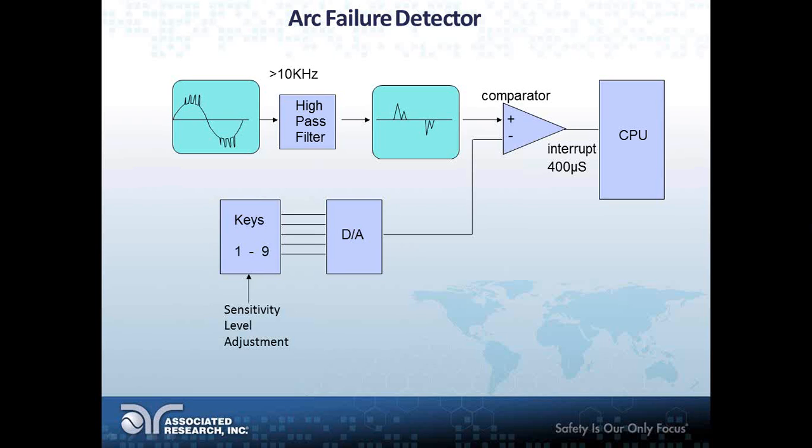So next thing, like I said, arc detection. I would like to cover arc detection a little more in this webinar. It's been covered in quite a bit of detail in the last webinar, but just a quick review of arc detection, since we had quite a few questions on this feature or function. Basically, the way our arc detection works is that high impedance arcs and corona generate high frequency current pulses that ride on the low frequency wave of the applied test current waveform.